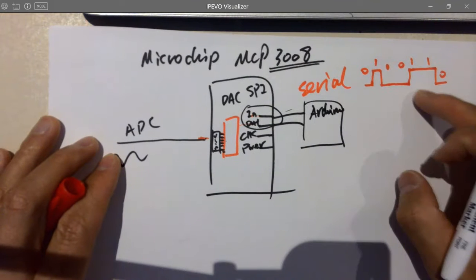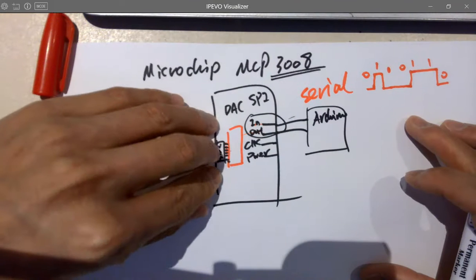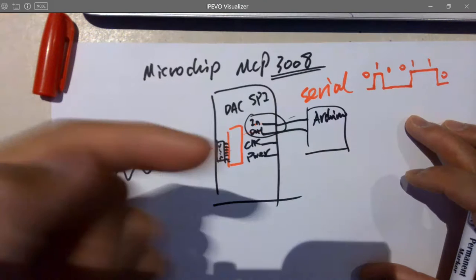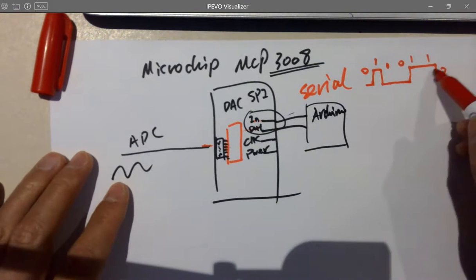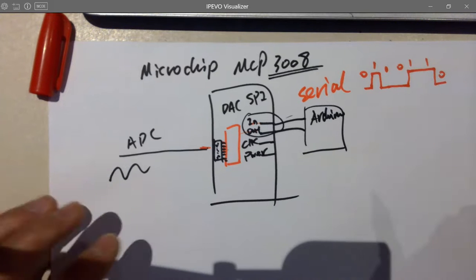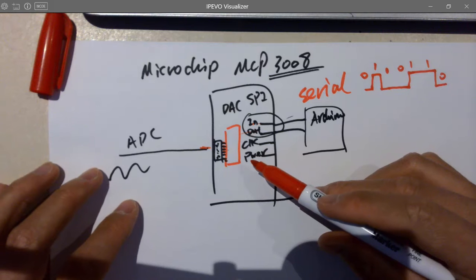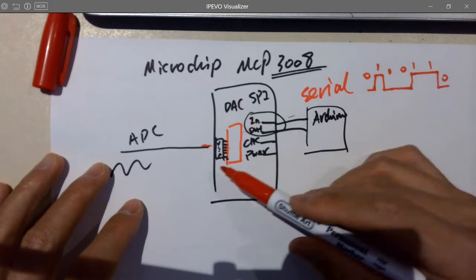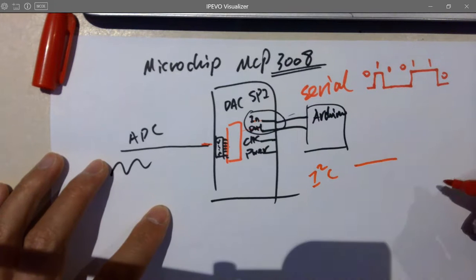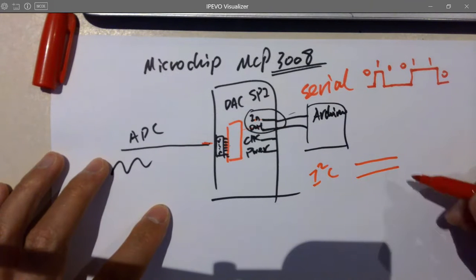And it has to be done in that way because there are 8 pins in parallel, and you have to send everything to a register and then pump them out one by one. So you are getting a serial output, not parallel. So why do we want a serial output instead of parallel output? Yeah, it's taking a lot of pin resource on the board, taking a lot of space. So you prefer to reduce the number of the pins. So SPI is one of them. There's another one called I2C, just one wire. Actually, two wires. One is for clock, one is for data.